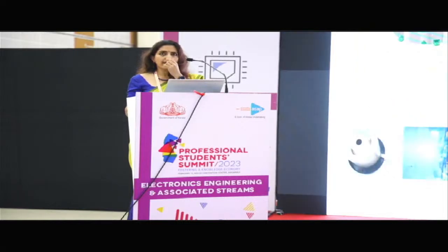These are some ongoing developments. We have 1 Newton thruster, as I already told. Then we have some low power also, because this is the age of micro and nano. We have some small thrusters also, and we have RF powered, which actually converts DC power to RF, then gives the thermal energy for the electrons to eject. So that is also one thing.